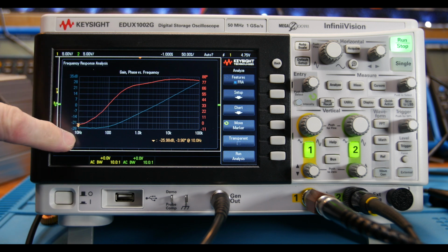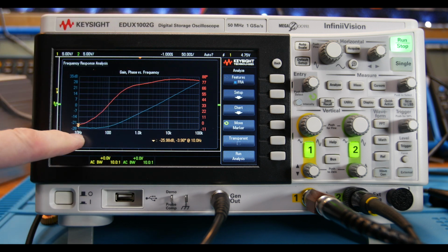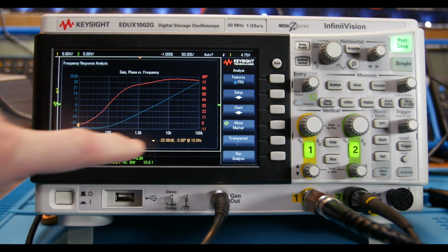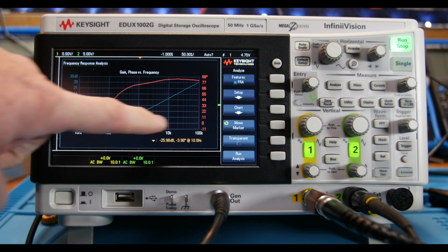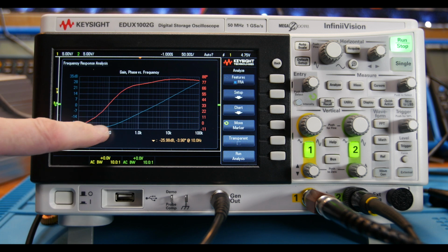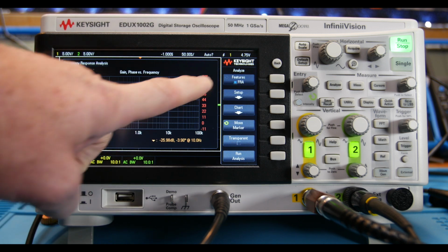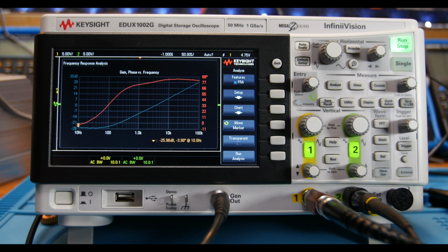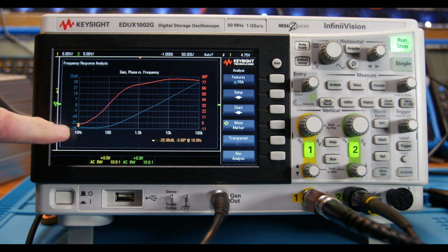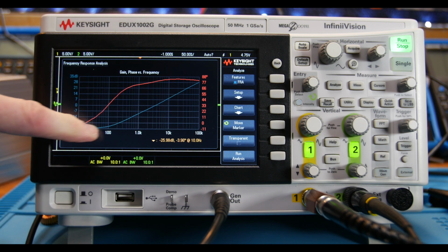On the blue side is the decibel scale, and on the red side is the degrees. The red waveform started down here around 0 degrees. At low frequency the impedance is pretty low on an inductor, and that looks to be true. It's close to minus 28 at the bottom grid, so it's minus 27 dB, and then right around 100 Hertz it starts looking like an inductor. That looks like a pretty darn straight line, a pretty good inductor. But below 100 Hertz it looks more like a resistor. There's not much impedance, so all you see is the DC resistance of the coil.